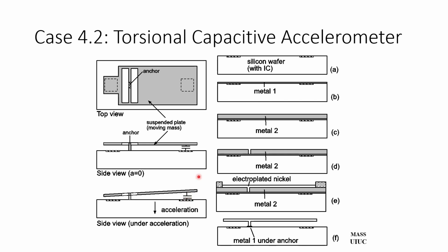Now, this can be done with a surface micromachining process. We start with a silicon wafer. You go through the routine oxide growth, patterning oxide to dope selective regions to have high conductivity.